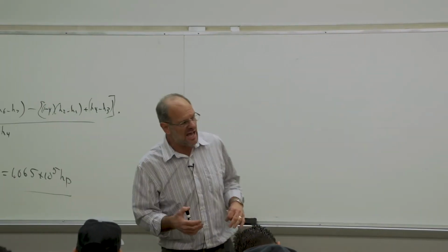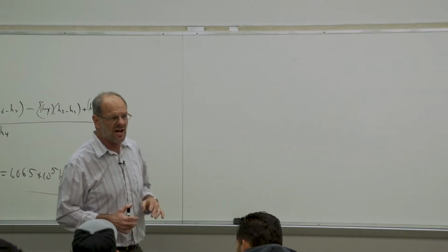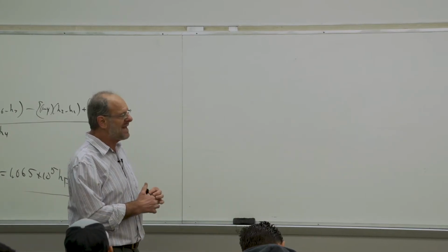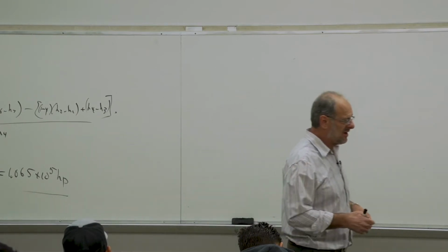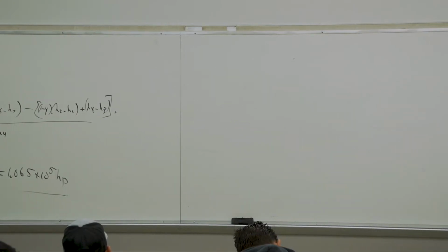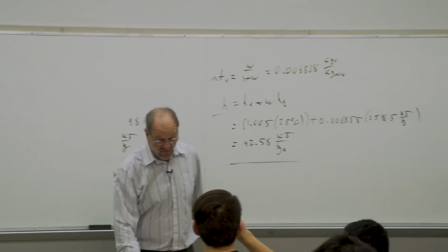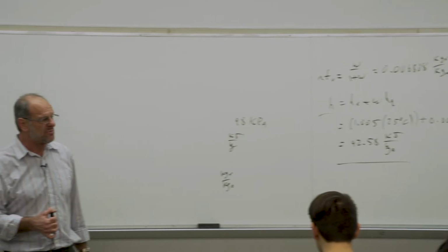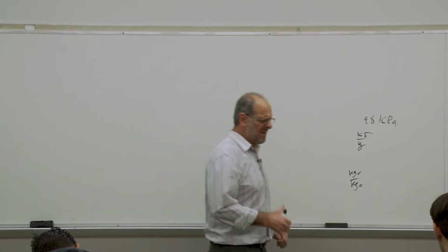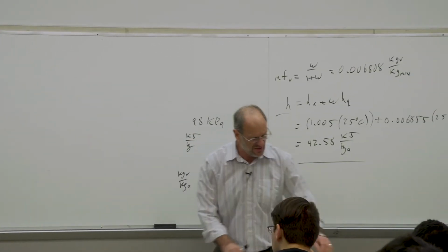There's mass being added or removed, so that implies a continuity equation, or conservation of mass. We've got lots of different possibilities. We certainly have to look at all of our problems in the context of air-water vapor mixtures and using data for air-water vapor mixtures. So a lot of information is now being considered.